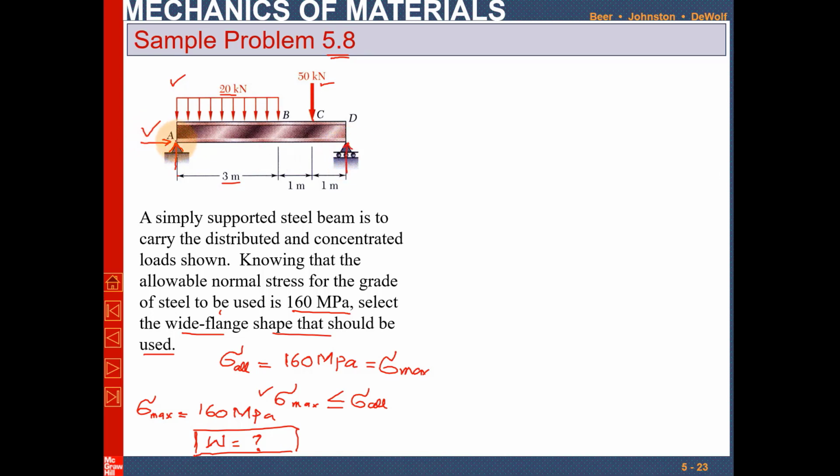At point A there is a horizontal force as well as a vertical force, and at point D there is only a vertical reaction force. So RAY, RAX. Clear? So how will you solve this to find the reaction forces? Basically you will use the equilibrium conditions: the sum of all forces along y direction is equal to 0, and the sum of all moments must be equal to 0 about any point. So let's start.